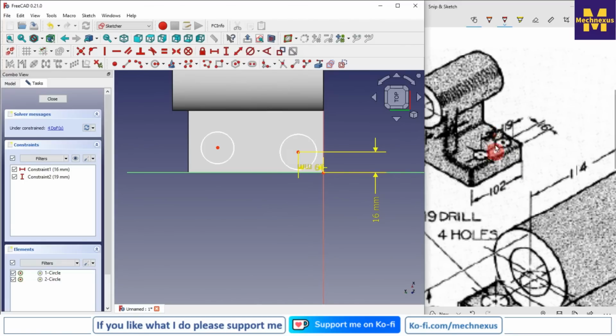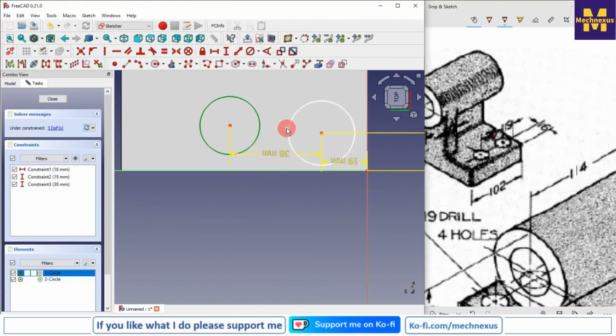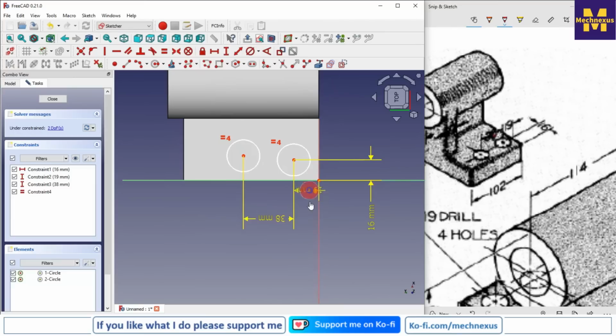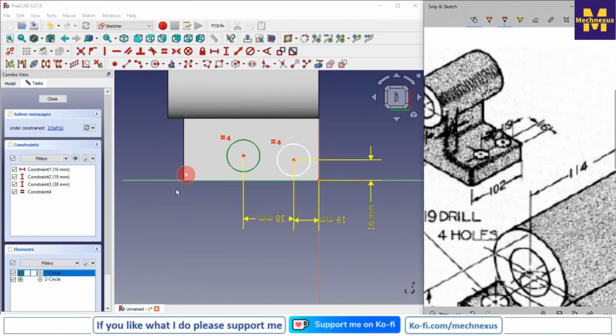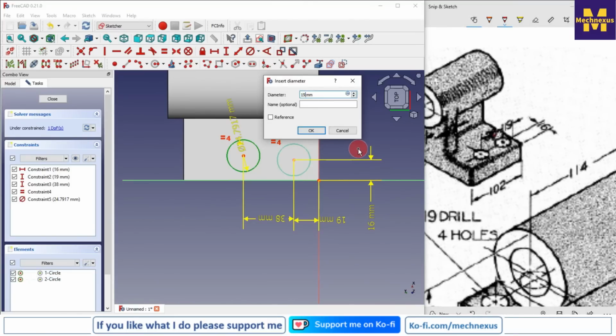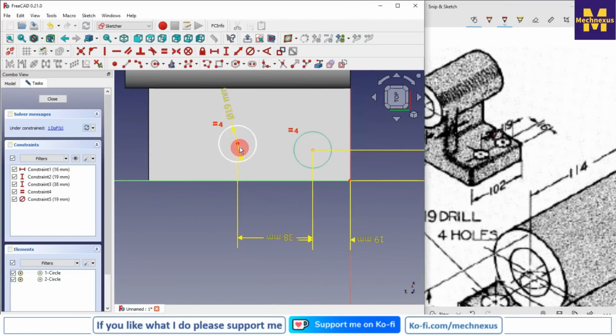And this seems to be 38, so I will select this and this, 38, and I will make an equal relation, say equal, and now I will give the drill size of 19, so I will give a diameter of 19 mm, and I will add the relation.